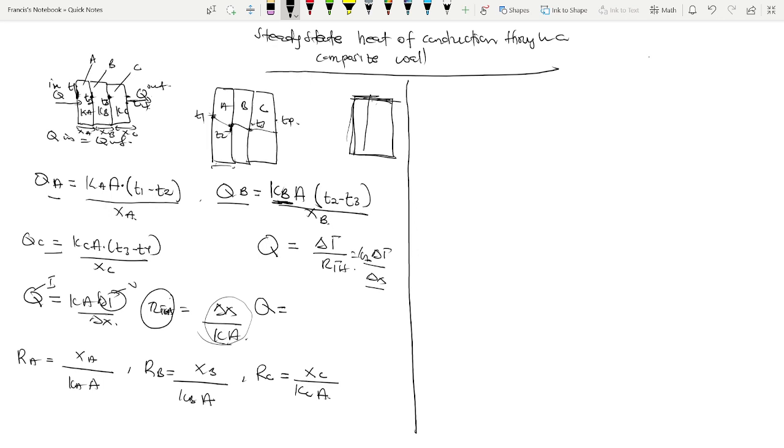So it means that we can write our rate of heat transfer to always be temperature difference all over thermal resistance. So we can write this as a heat transfer equation henceforth. This is what we're using henceforth. We don't need to write everything again. And if you are dealing with conduction, our RTH is change in X over KA, and then we can calculate the RTH separately, and then divide the temperature difference by it to get our heat. So that's what we are doing here.